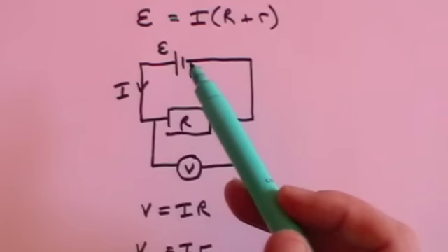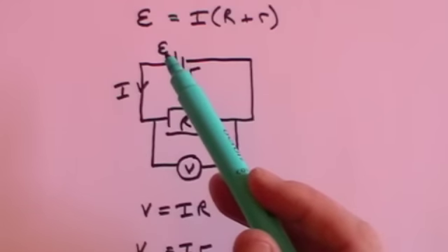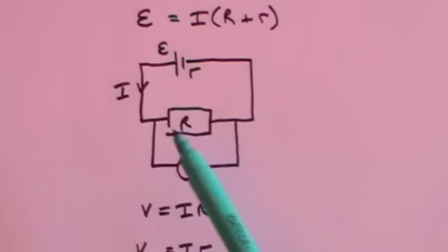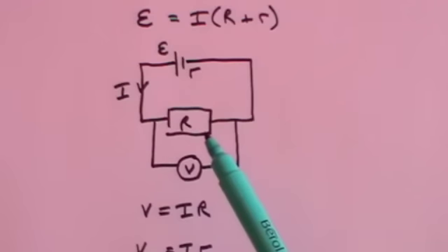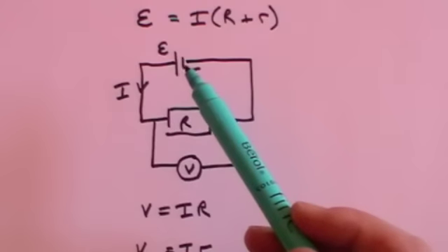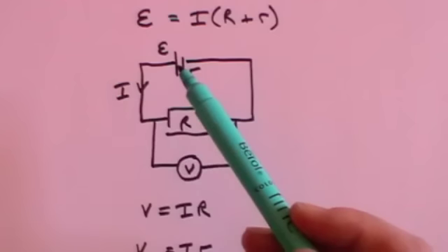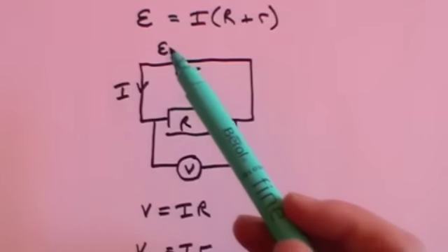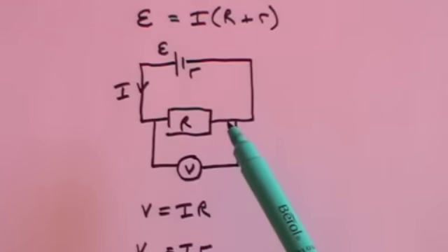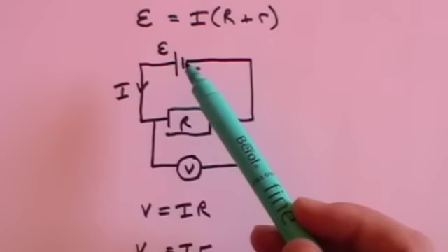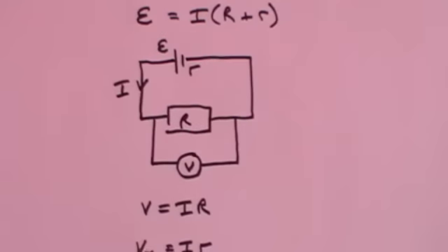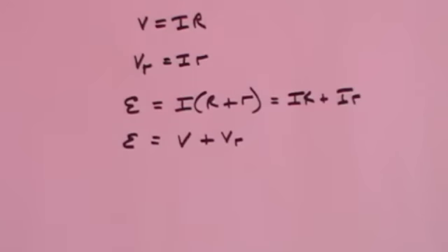So now you've got this peculiar situation that the inherent voltage of the battery, E, the EMF, is principally dropped across the main resistor, but not entirely. A little bit of that EMF will be, as it were, dropped across the battery itself, because the battery itself has an internal resistance. So normally we would have said that the whole of the battery has a potential drop across the resistance. That is no longer the case, because there's another resistance in series, and that resistance happens to be inside the battery. So there are a variety of ways of writing this value of E now.